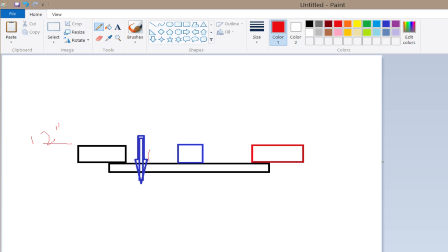My drill bit's going to jump up to 1, and it's going to wrap it over and slam into this clamp and break the drill bit in order to drill that second hole. Does that make sense? So you need to make sure that your clearance level is going to get up above your clamps before it goes over to the next part.